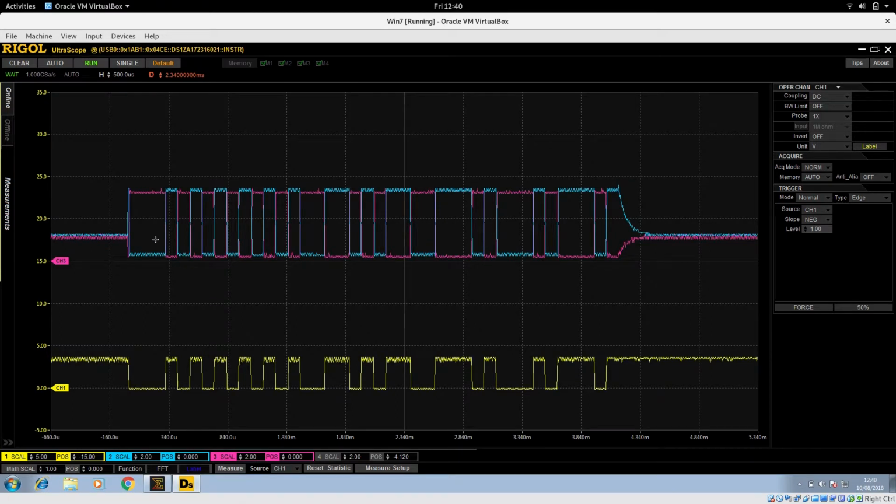And then you can see the differential signal. So all our RS485 transceiver is doing is monitoring the input and then just setting A and B accordingly. And once we're finished, we drop the line. We tell the RS485 transceiver we're finished transmitting, and the two voltages... Now if the biasing resistors were there, this drop would be very different, but the two voltages return to their idle condition. We're finished transmitting.